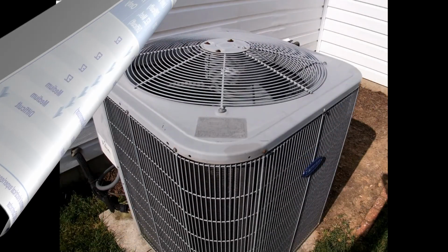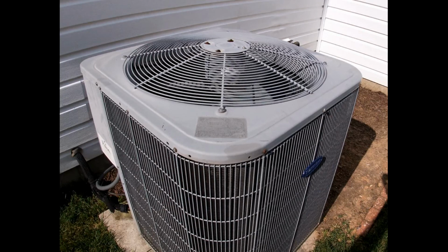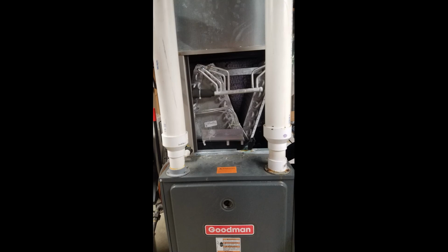As I mentioned in episode 28, your air conditioner is a sealed system that is charged with a proper amount of R410 refrigerant, liquid and gas. If a significant amount of this refrigerant leaks out of the system, your air conditioner will not cool. It's possible that you could have a leak outside here in the condenser or inside in your evaporator or any of the line joints carrying the refrigerant. Frequently when you're low on refrigerant, the evaporator coil inside will freeze over.